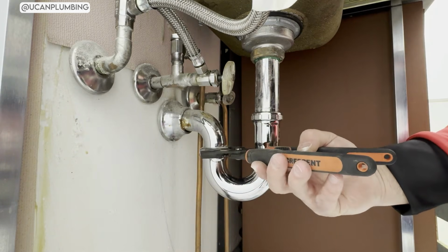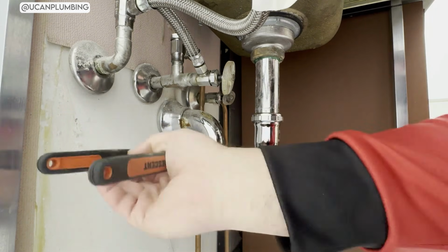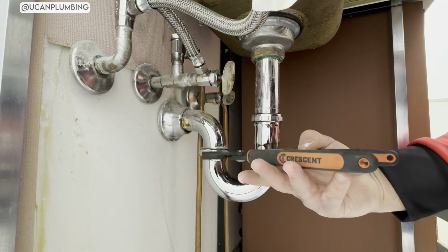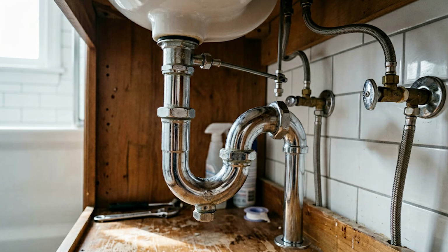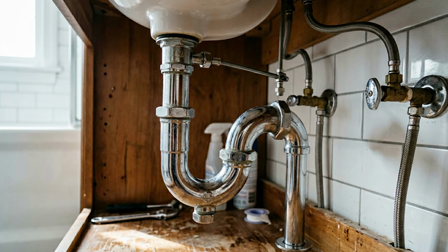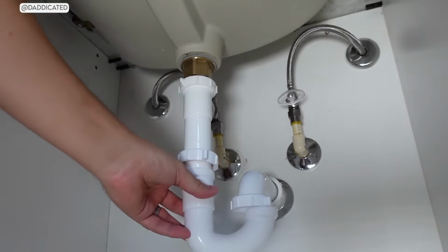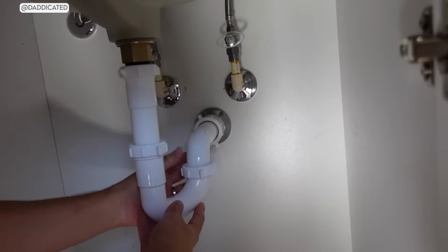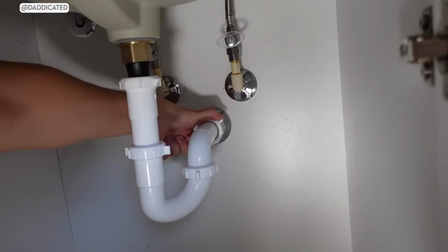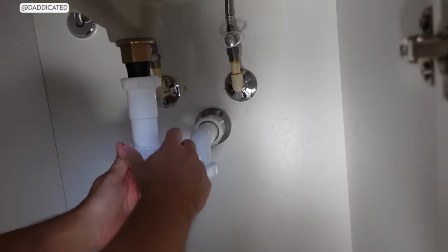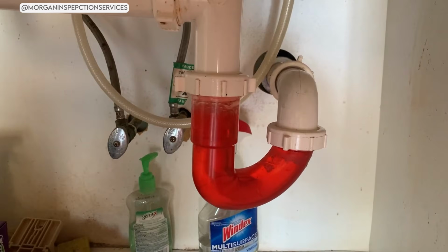The standard plumbing codes require a trap seal depth of at least 2 inches, but no more than 4 inches. That is not a random number. It is the sweet spot where you have enough water to form a reliable barrier, but not so much that the drain becomes sluggish or hard to clear.